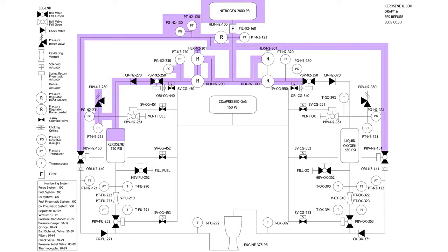system that's sitting up against the valve with the 750 psi fluid above it. And so everything wants to flow from high to low. And so because the pressure above that 750 is eventually 2800, when we open valve 253 on the fuel side, it needs to flow towards the engine. It has no choice. It can't flow backwards. That's the way it's designed, everything flows from high to low. And so you have that check valve as well. Yes, and we have a check valve to prevent any backflow. Correct. So that check valve is just there in place to protect us.